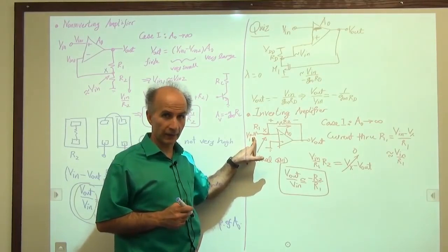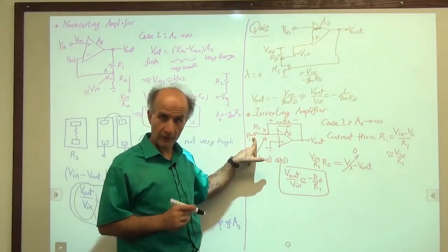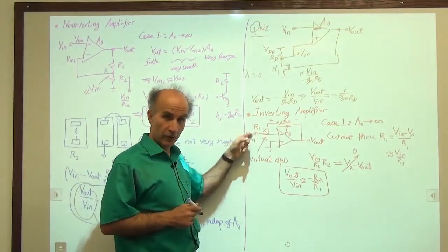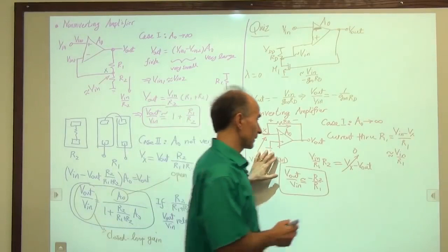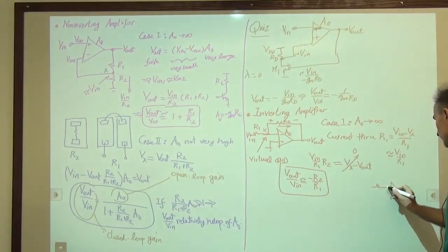We can quickly find that, right? How do we find the input impedance? We kill all the independent sources in the circuit. We apply a voltage from outside and measure the current. So let me do that on this side, just so you see how this is done.